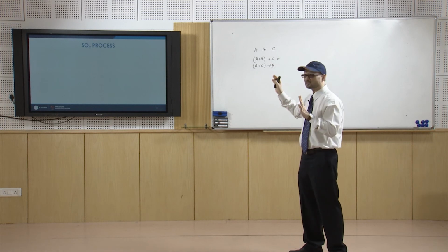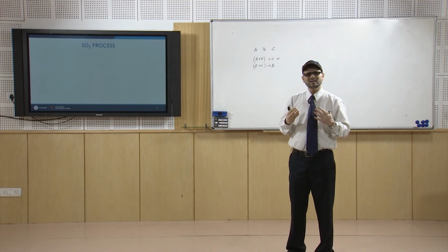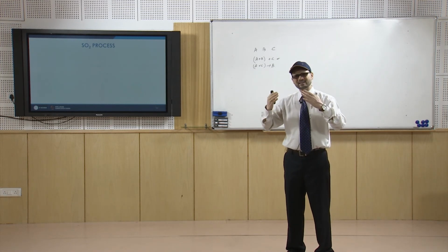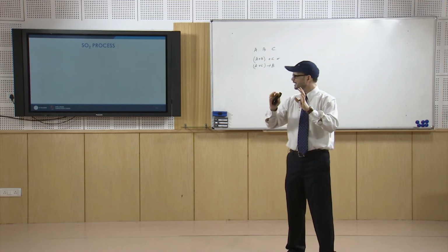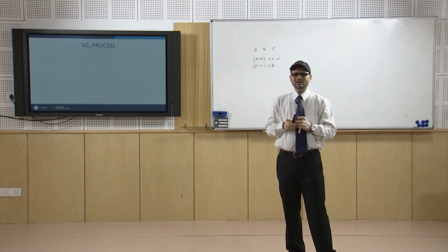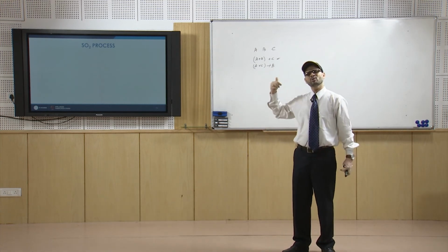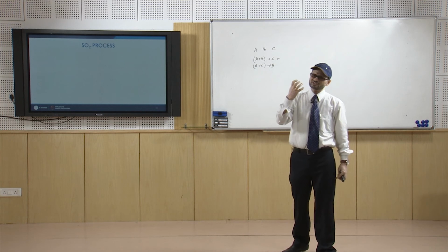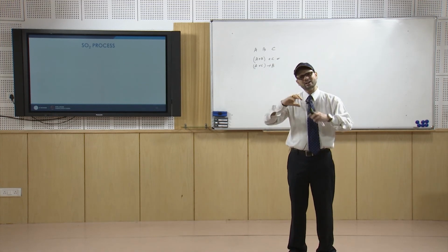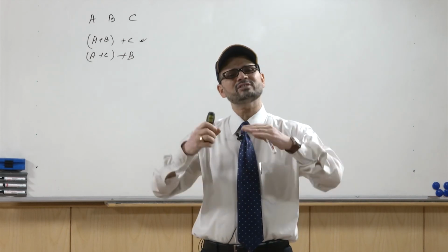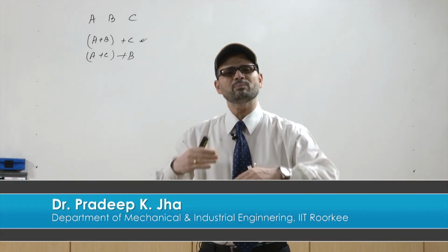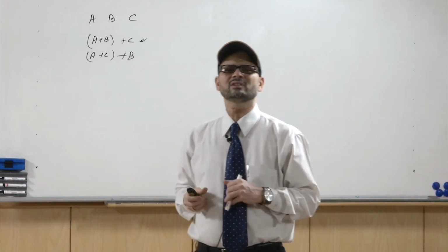But these are the different kinds of methods used for making molds using organic binders, and they are used quite extensively for making cores, because they take very less time. What needs to be mentioned is that in most cases the bench life is quite short. The flowability is quite good but the bench life is short, so they are to be used quickly. The production rate is quite fast, so they can be used for mass production.